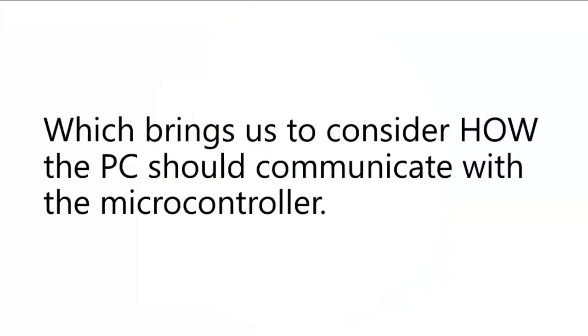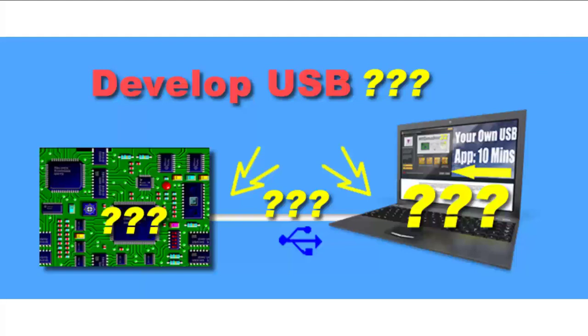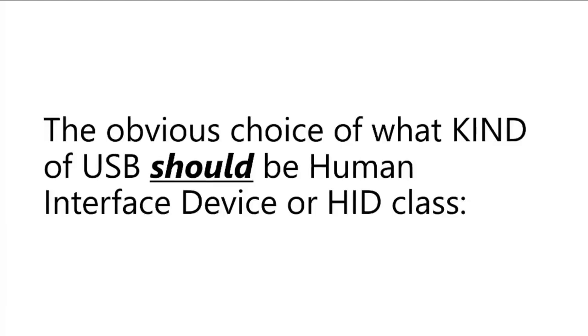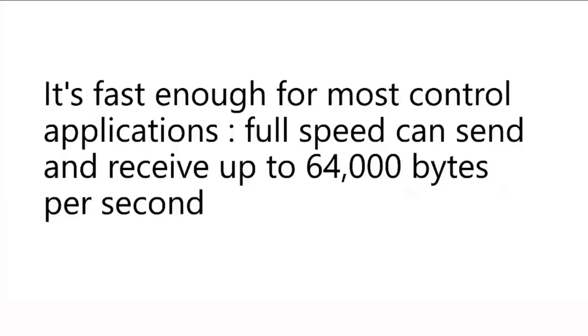Which brings us to consider how the PC should communicate with the microcontroller. The obvious choice these days is USB, but what kind of USB? The obvious choice of what kind of USB should be Human Interface Device or HID class. It's fast enough for most control applications.